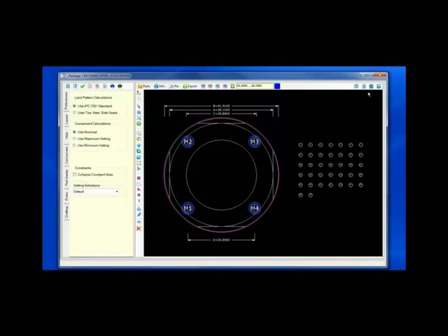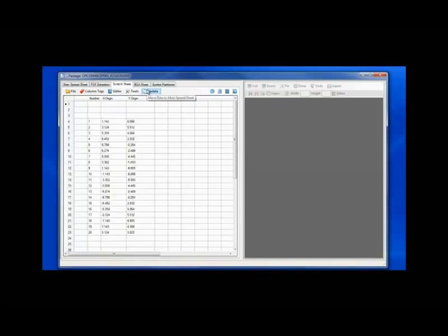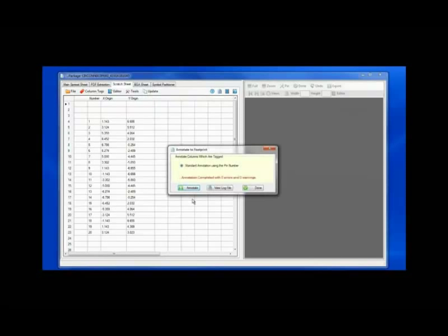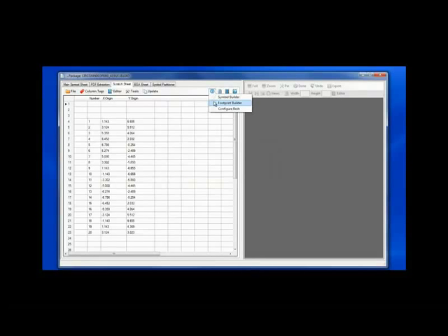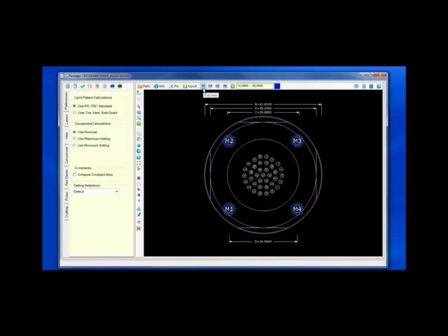Let's go back to the symbol builder, integrated right directly into the product. And under Update, we will now annotate the PDF datasheet extraction to the footprint model. Completing the annotation, we will configure back to the footprint builder. And notice that the pins have been moved to the XY coordinates from the datasheet.